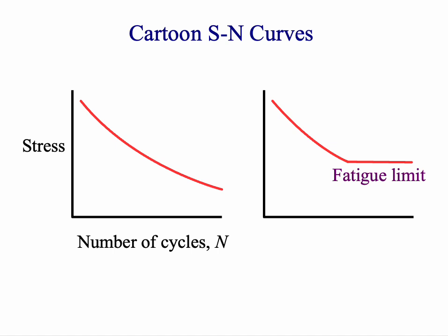In fatigue testing, you apply a load, you release the load. You apply it, you release it, and keep on going until the part breaks. There's a diagram in the book of the earliest fatigue testing machines for rotating axle shaft materials, and we still run rotating bending fatigue tests that same way.